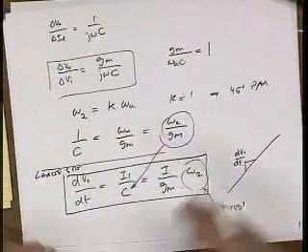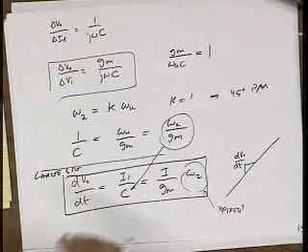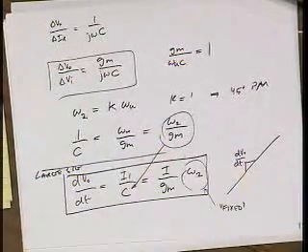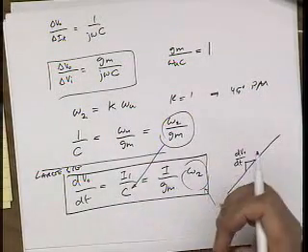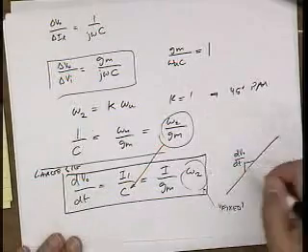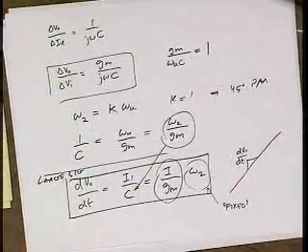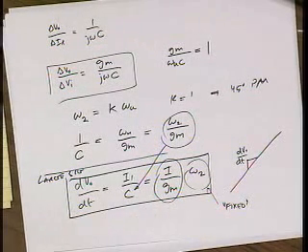Because it has to be, let's say, 3 times the frequency of unity gain, right? So it's kind of a fixed number. Usually I'm designing an amplifier with a given frequency response that I want to achieve. And so the only way to improve this ramp is to make this ratio larger. Okay. Now earlier in this class, we looked at this ratio very carefully, right?